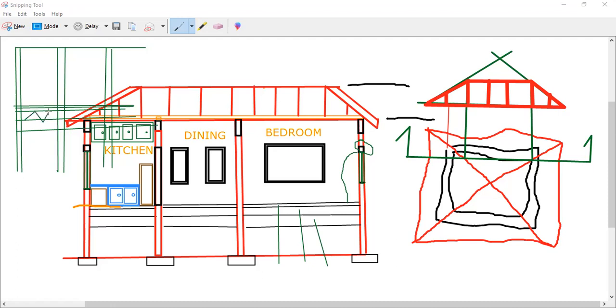We would extend this out, then offset this line down to the depth of our foundation, and that ranges from 300 to 1200 millimeters. Of course, we typically don't use 300 millimeters unless they're building on solid rock. We typically use 900 up to 1200.